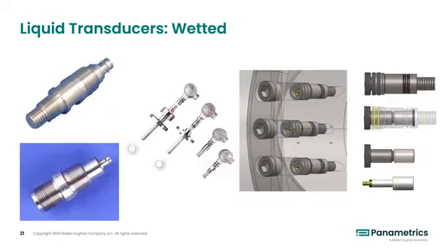Wetted transducers for applications are used in both the PanaFlow and the Sentinel product lines. The WT and BWT transducers on your left are used in higher temperature processes in conjunction with various buffer assemblies to allow for measurement in extreme temperatures.